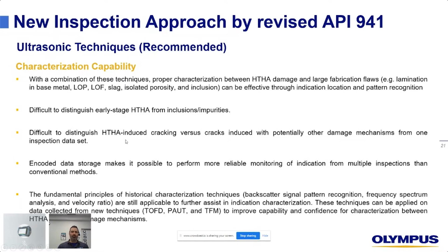Difficult to distinguish HTHA-induced cracking versus cracks induced by potential other damage mechanisms from one inspection data set. Again, why we want to use more than one method. With phased array, with TOFD, with also a proper ultrasonic or phased array instrument, you can record your data, have it encoded, and go back to your data, monitor the growth over time, which is a key advantage compared to the conventional or historic methods.